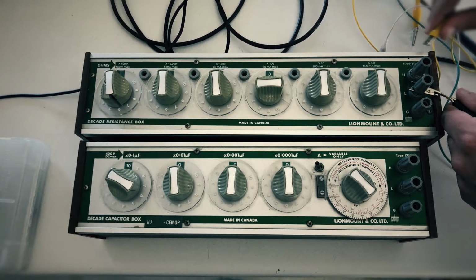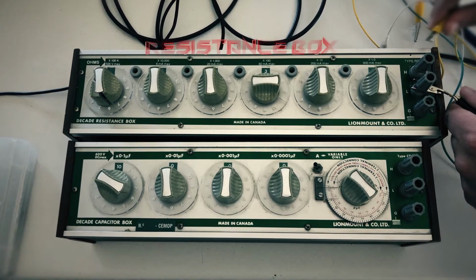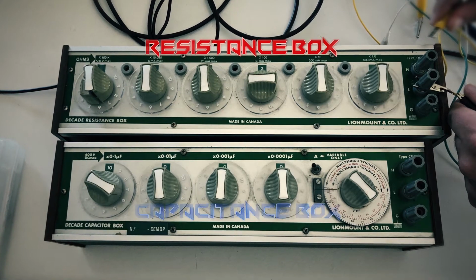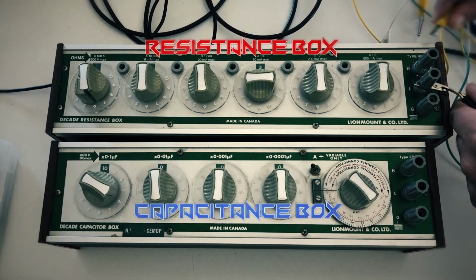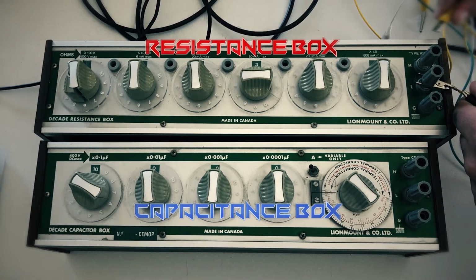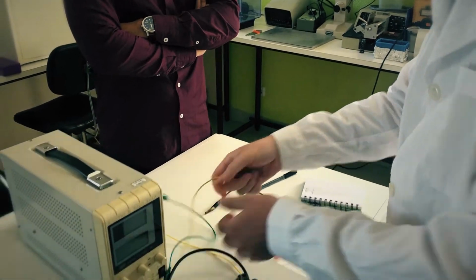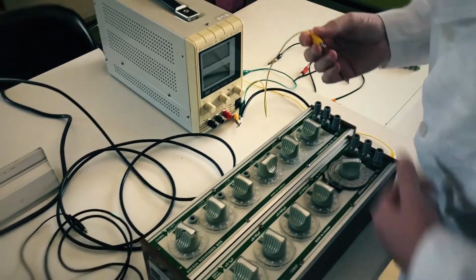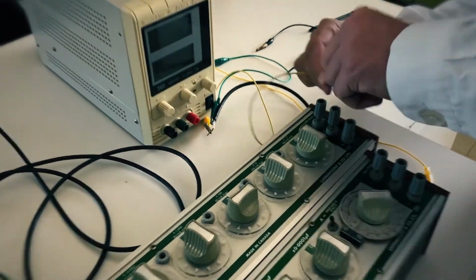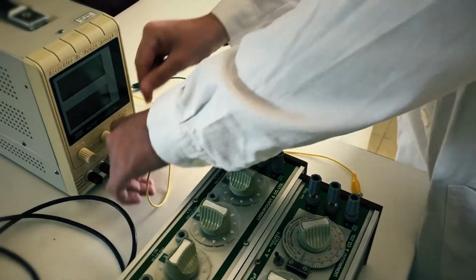In order to observe the effects of the internal resistance of the photodiode in its response profile, we use a resistor box which allows for varying resistance values. Similarly, a capacitance box is also necessary to simulate the effects of parasitic capacitances and/or to observe the effect of the junction capacitance. The resistance should be added in series and the capacitances in parallel. This way, we should also be able to observe, from a practical perspective, the effect that both of these components have on the photodiode's response time.